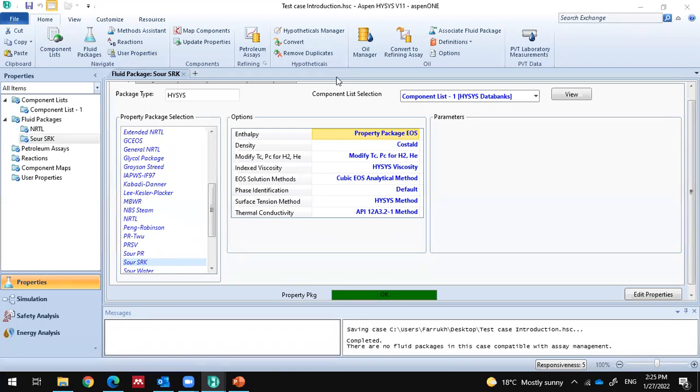What if I had a mixture of polar and non-polar? Yes, this is what I said. In that case, if it is a mixture, then you need to do a thorough search and try to find out if there is some information available in the literature. If you have the interaction parameters, I think you can then go with NRTL or this set of equations. Pseudo means a user constructed mixture? No, not a mixture. Pseudo means a user constructed component in Hysys. I'll show you in a while.